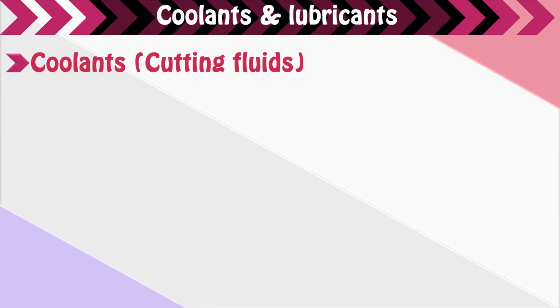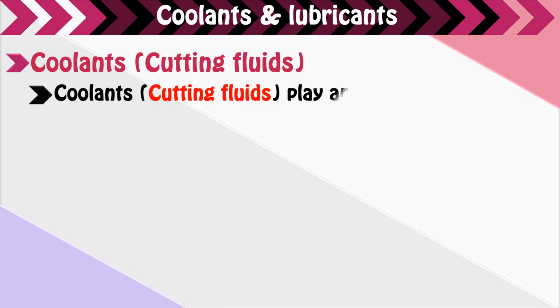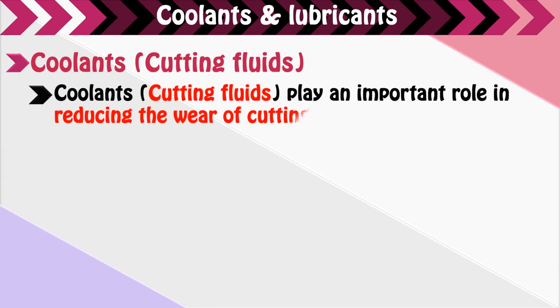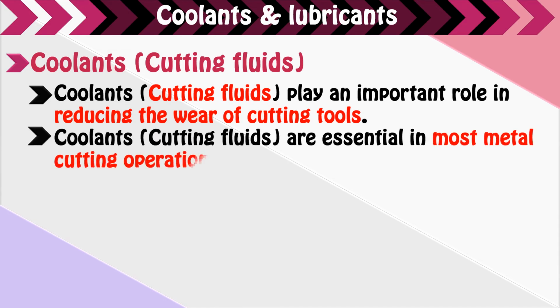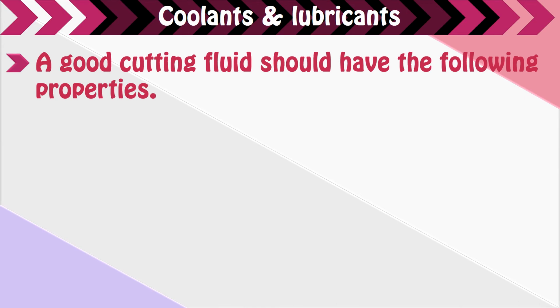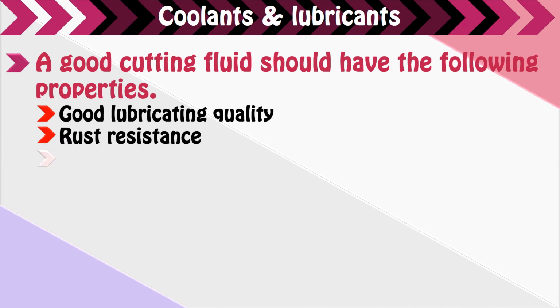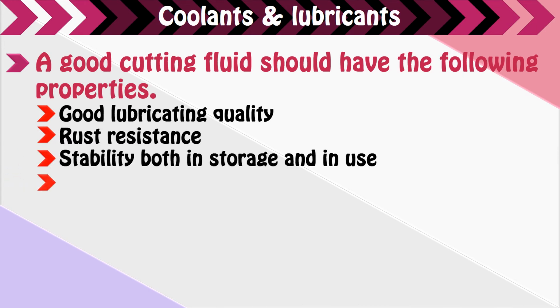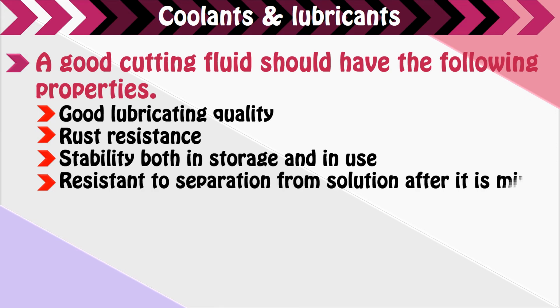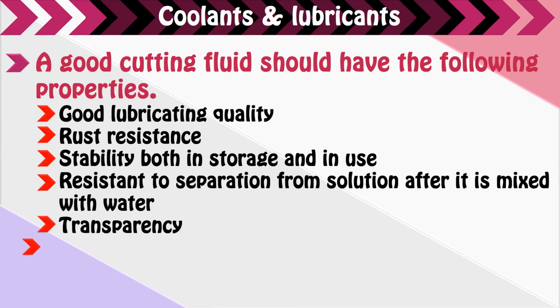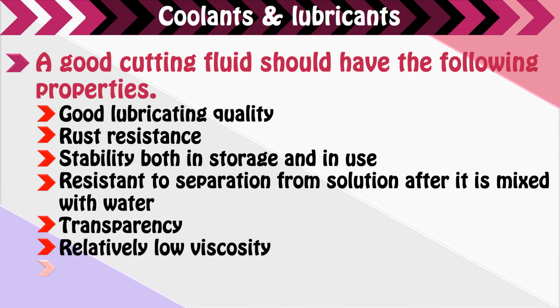Let's see about coolants, also called cutting fluids. Coolants, or cutting fluids, play an important role in reducing the wear of cutting tools. Coolants, or cutting fluids, are essential in most metal cutting operations. A good cutting fluid should have the following properties: good lubricating quality, rust resistance, stability both in storage and in use, resistance to separation from solution after it is mixed with water, transparency, relatively low viscosity, non-flammability.